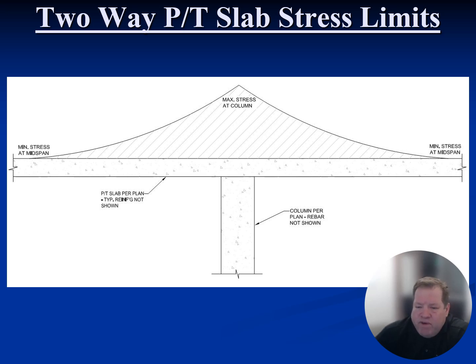But because you have a singular point of support, this is where the stiffness comes from. This is where the max moment, max stiffness, the max stress is going to be generated. And as you go away from the column, you don't have the stiffness anymore, and so the distribution of moment is going to go down. So the stress across this entire trib width is not going to be one single value, but it's going to be a whole series of values as you're seeing here.